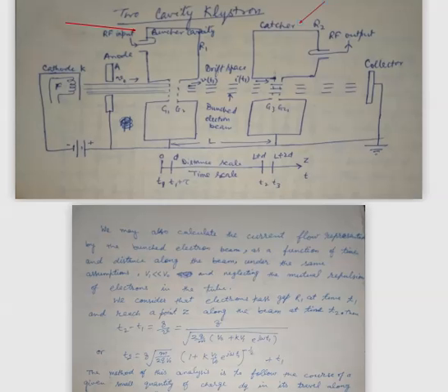Now when the electron beam passes through the catcher cavity grids, the distance capital L between these two cavities is optimized so that each electron cluster after the bunching process, when it passes through the cavity grids G3, G4, will be retarded.